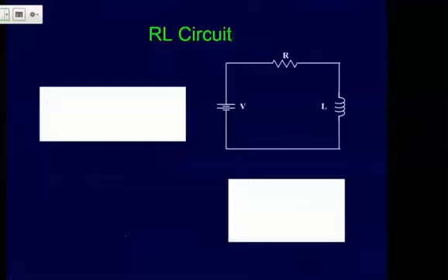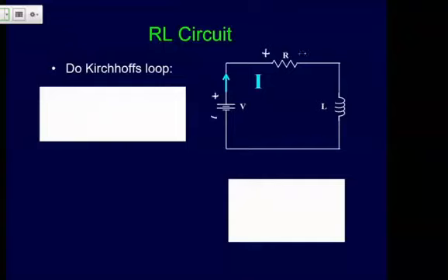All right, so now we're going to look at this in a circuit, just like we did with capacitors. So there'll be some analogies to capacitors. What you can often do is set this up. Here's a nice DC battery with your resistor and your inductor. Let's say that we start our conventional current like this. If I do my signs, I'll get a positive and negative there, positive, negative there, and then positive, negative there. So again, the current is just starting out.